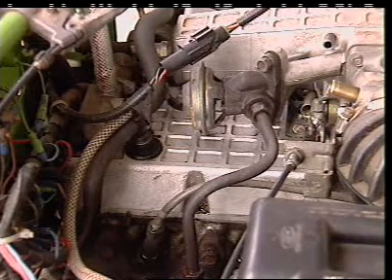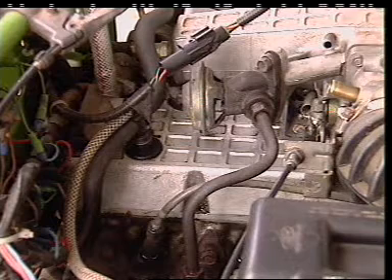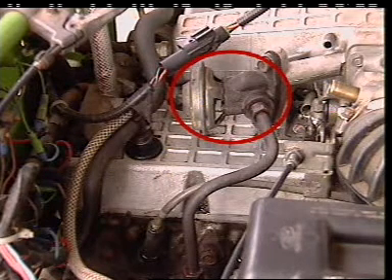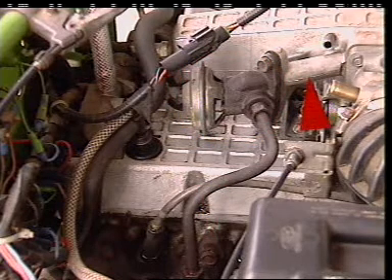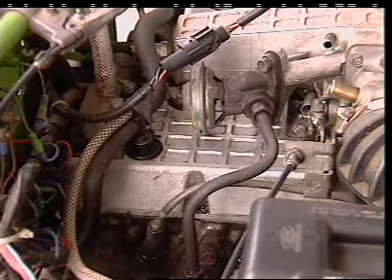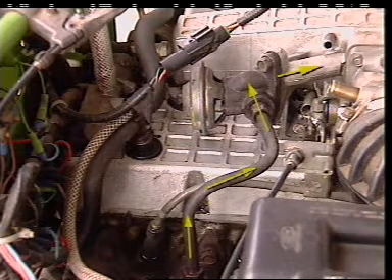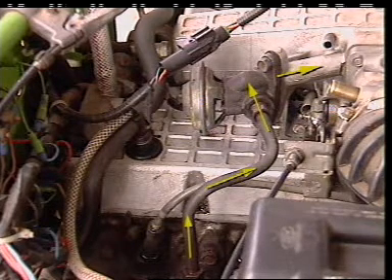If valve overlap is maintained or even increased, oxides of nitrogen can be reduced by an exhaust gas recirculation, or EGR, valve connected between the exhaust port or manifold and the intake system. If engine conditions are likely to produce oxides of nitrogen, the EGR valve opens, letting some gases pass from the exhaust into the intake system.